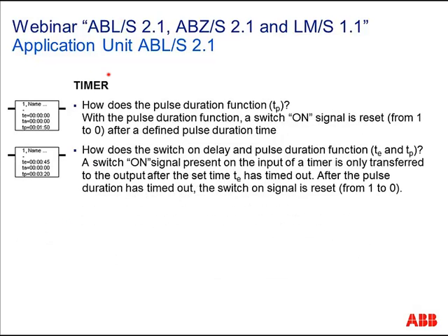So what about this pulse duration? Pulse duration works on the principle of a staircase. Like here, on the input it receives the value 1, and then the 1 minute 50 pulse duration starts. And after 1 minute 50, it sends the off signal, the 0, to the KNX bus. This works like a staircase function.